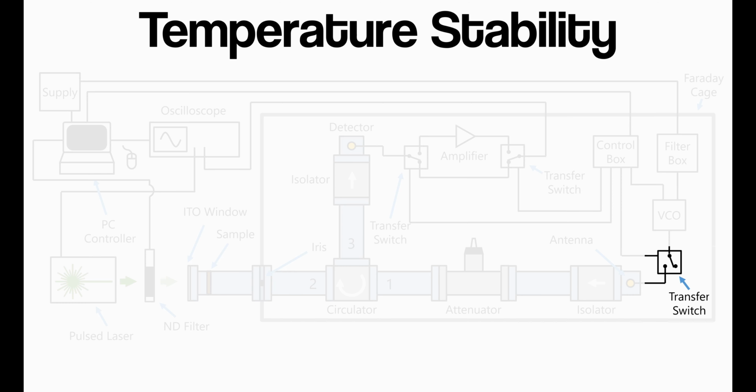In itself, the temperature is not a problem. The problem is that the output voltage is also going to be slightly dependent on the temperature of the unit. And what this means is that if you initially turn on the VCO, it will output a certain frequency for a certain voltage, but as the components heat up, this may drift and you may get an unexpected output frequency.